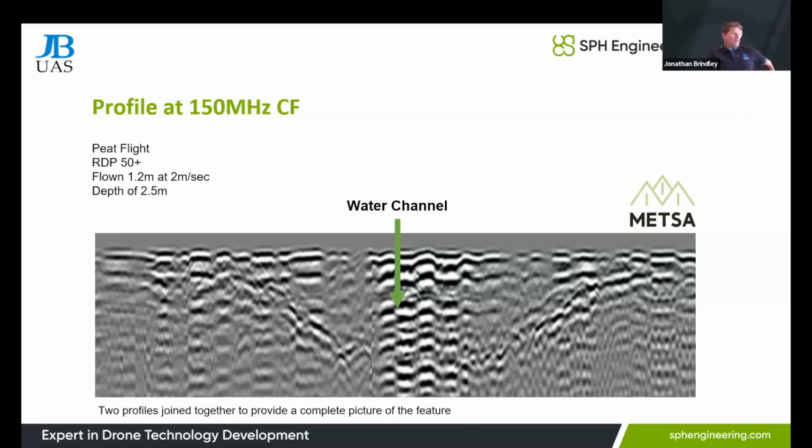So ideally, I would suggest flying, and I wasn't actually present at this particular flight, but I would always recommend flying the LFGPR at probably around 1 meter a second. This was flown at a quicker speed than I would recommend, just to make sure that you get that resolution.